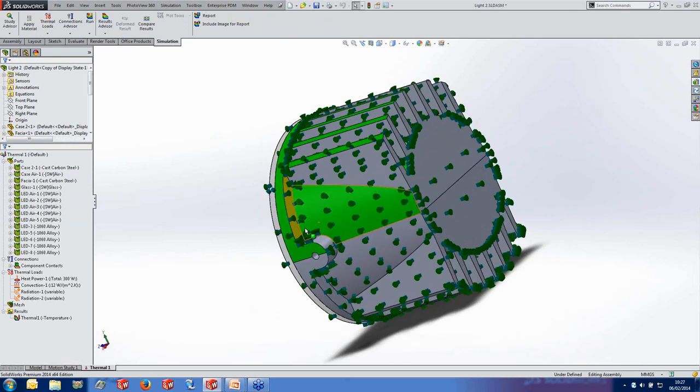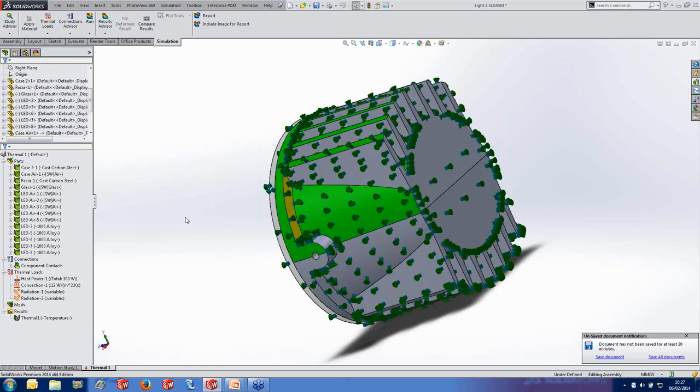Now, because I haven't added fillets to it, it's not as bad as it could be, but obviously we would want to go through and have a look at fillets for the same reason we wanted to have a look at fillets for the previous case, because they're going to make it easier for the mold maker and make the mold more durable for producing more parts. But for simplicity within the simulation, what happens is I ignored them.